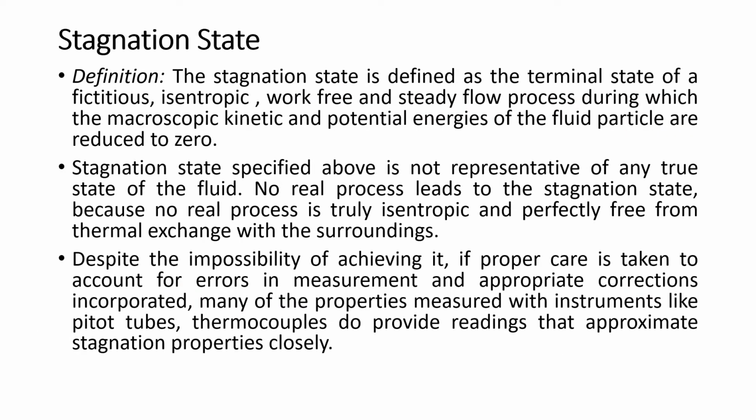In the previous slide, we understood what is static state. So if you want to measure the static properties, then there should be no relative motion between the measuring instrument and the fluid particle. That can be done in two ways. One, moving the measuring instrument along with the speed of the fluid particle.